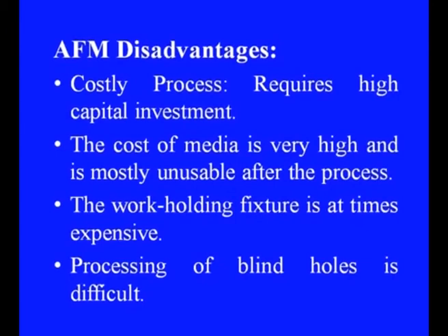Then there are certain disadvantages as well. Basically, this is a costly process. This requires high capital investment. The cost of the media is very high and it is mostly unusable after the process. Recently, some reusable media have also been developed that we will discuss in subsequent discussions. That is again the development of IIT Roorkee. The work holding fixture is at times expensive. Processing of blind holes is difficult in this process.